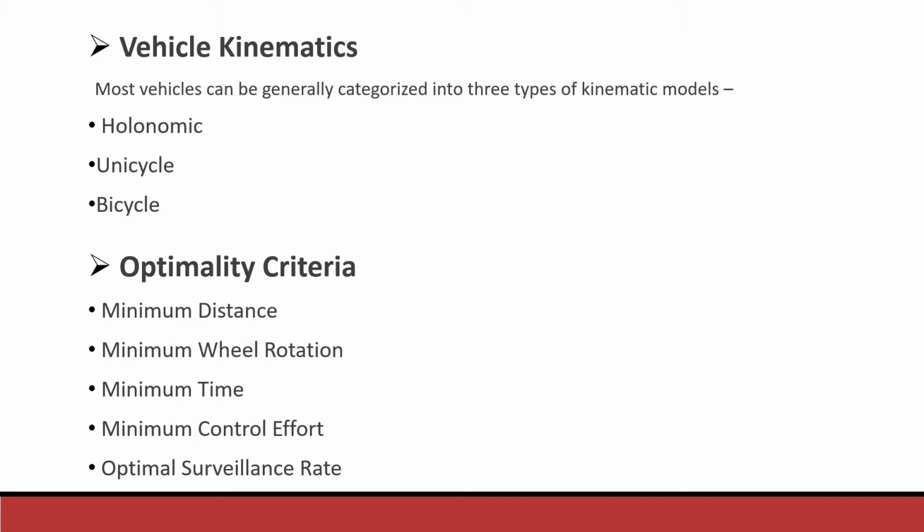This applies to differential drive robots and in most cases differs only slightly from the minimum distance formulations. However, it may perform better in some situations, especially when fine movements are required. Minimum time. Calculating the traversal time of a path depends on the velocity profile of the vehicle and thus includes kinematics. It would be more appropriate than minimum distance for selecting the trajectory that completes the task in the most efficient manner. It is often used in MPC based approaches.